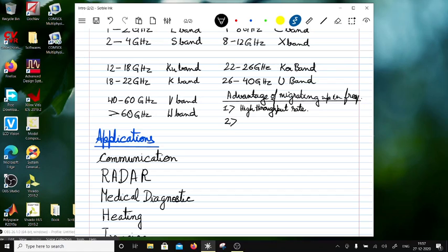Second and very obvious reason for going up in frequency is that there are 4 kinds of noises. Ignoring all the interference noises, there are 4 kinds. These 4 kinds of noises are, first, flicker noise. Flicker noise is usually in the active devices, and this has to do with whenever you have a junction between dissimilar materials, for example metal and semiconductor, or let's say silicon dioxide and silicon.